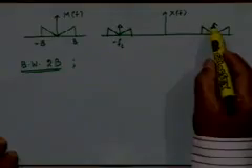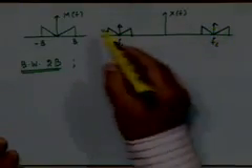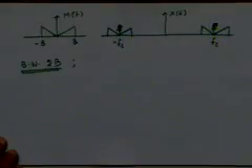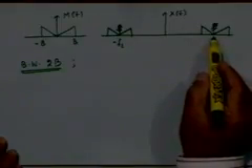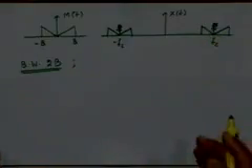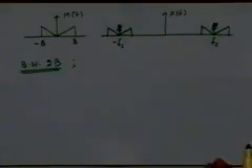No, I think you have not understood the point. We were not getting the carrier frequency information. We didn't have a specific carrier component at fc. For example, in this particular case, the suppressed carrier spectrum would look like this, right? So we don't have a component at fc. Just because the spectral density has some value at fc doesn't mean that there is a component at fc, right? Yes, you can say that there is some energy present in the neighborhood of fc, right?